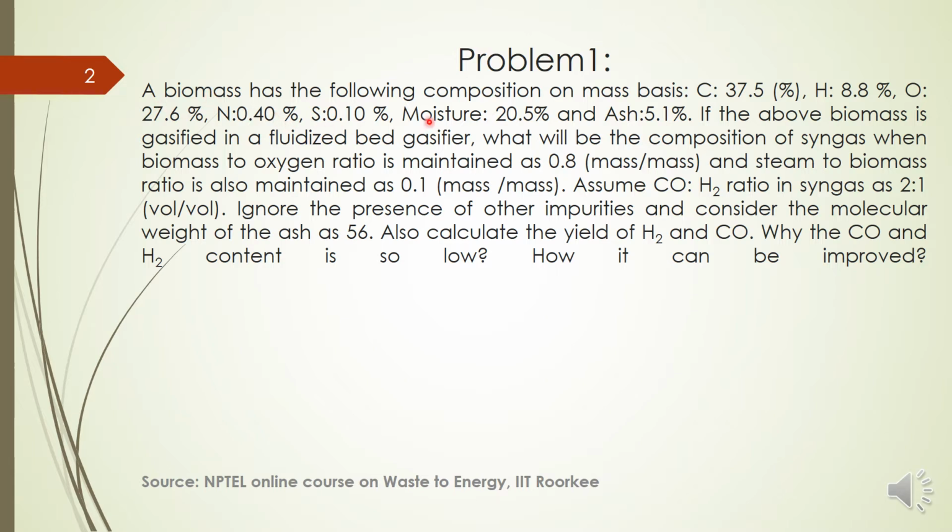A biomass has the following composition on mass basis: carbon 37.5 percentage, hydrogen 8.8, oxygen 27.6, nitrogen 0.4, sulfur 0.1, moisture is 20.5 percentage, and ash is 5.1 percentage. If the above biomass is gasified in a fluidized bed gasifier, what will be the composition of syngas?